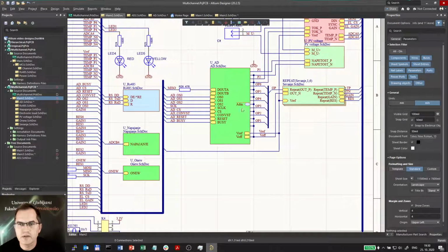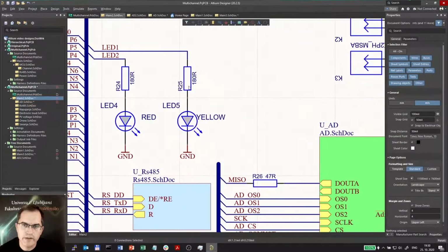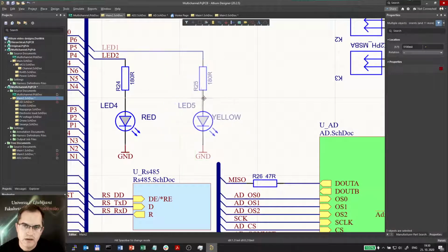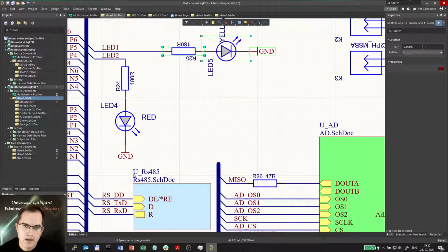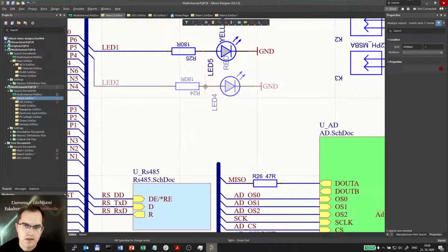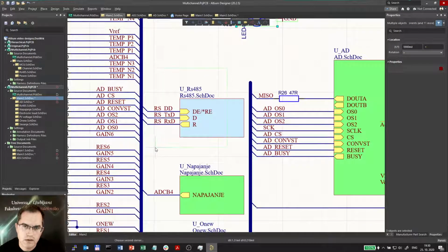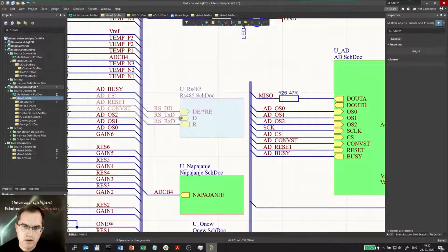I just have to replace all these wires with a single signal harness. For that I will need a little bit of space. Well, how to do that? I will go here and maybe just make a little bit space to make the schematics more neat. Okay, moving. And I'm always selecting from right to left so that I have the touching block selection. So let's say I'm satisfied with that. I will now move that one, touching block, moving upwards.